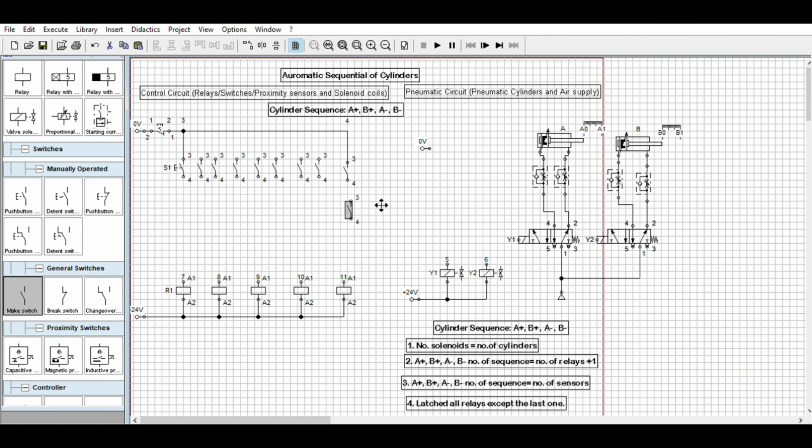Okay, when we say latch, normally open. When you say interlock, normally closed. Okay, all latching connect all together up. So the basic circuit there is the start-stop circuit, latching, emergency stop, or the normal stop. In pneumatics, electro-pneumatics, you also have that one, emergency stop or the normal stop.